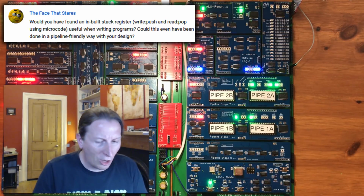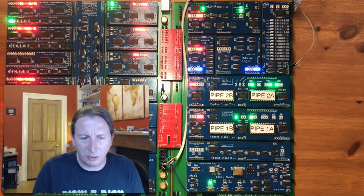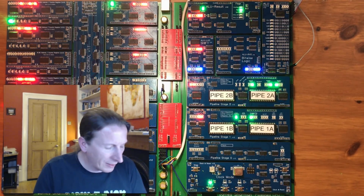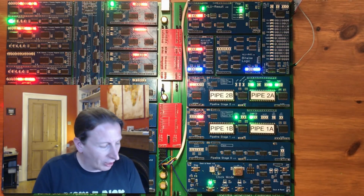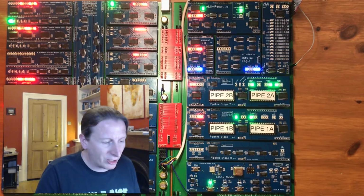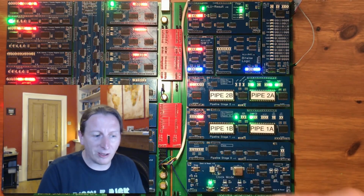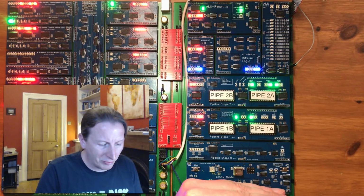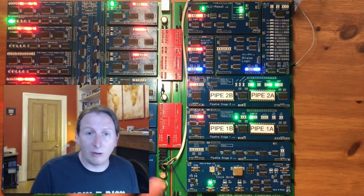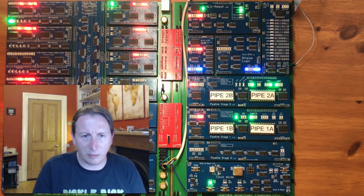So a load and an assert operation would both perform the data move but also handle the increment and decrement of the stack pointer. So that would have freed up a couple of control lines, and it would have also meant that the stack operations didn't take control of the main memory system, so I would have been able to do them back to back and have a slightly increased instruction throughput. But I didn't go down that road in the end because that would have been different from the way the stack works in most standard processors.